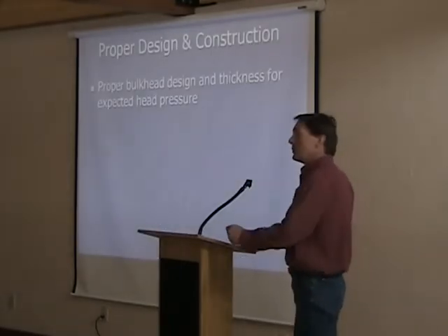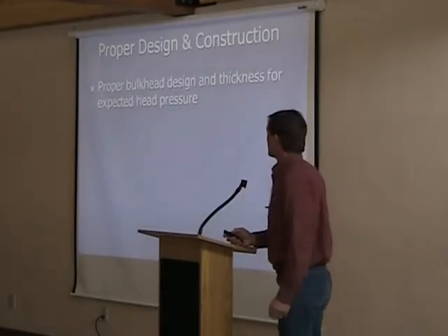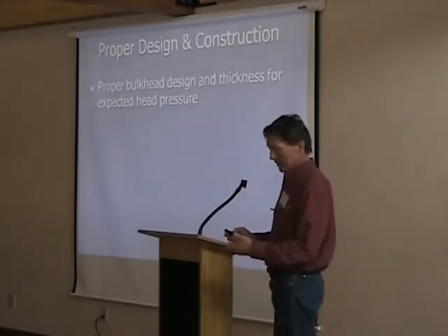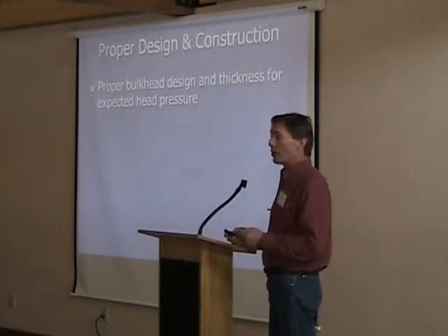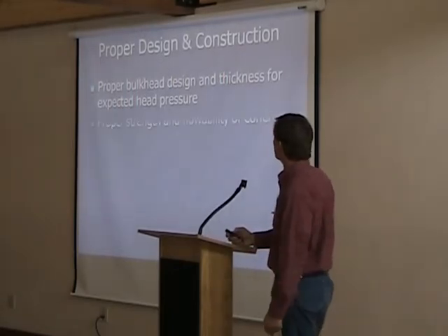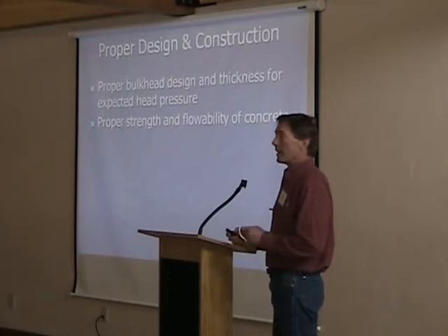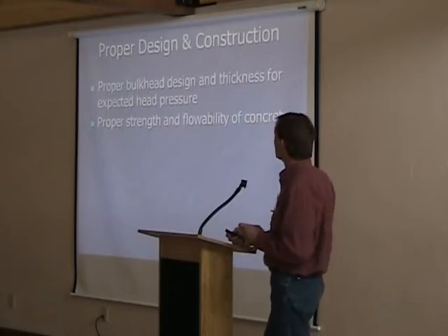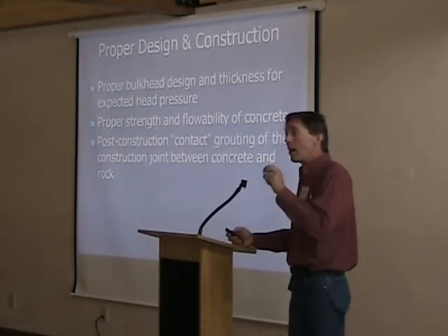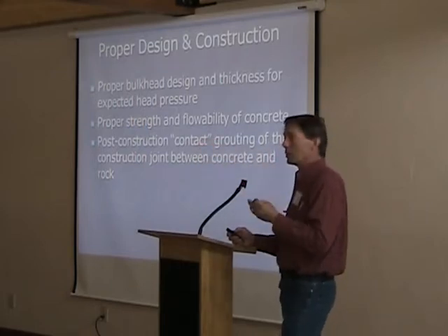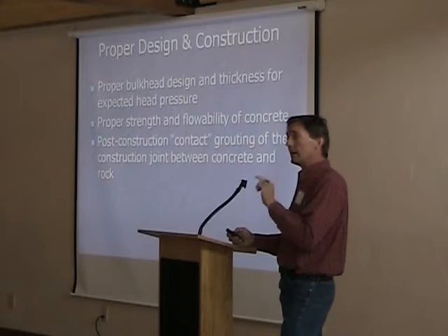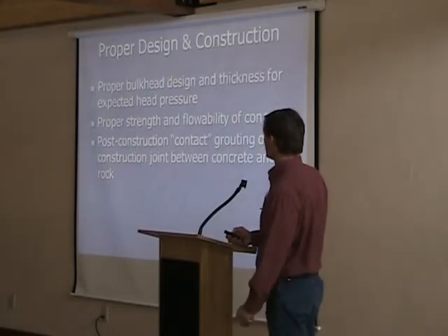So then, if you do find a good place to put a bulkhead, obviously the last thing you have to make sure of is that you properly design the bulkhead and you follow proper construction practices. You got to make sure that it's going to handle the head pressures that you're predicting. You have to make sure that you can pump concrete way back in, or deliver that concrete to get a good product where you need that in the bulkhead and the workings. So the mixture design and how you're going to actually place these deep underground bulkheads is critical.